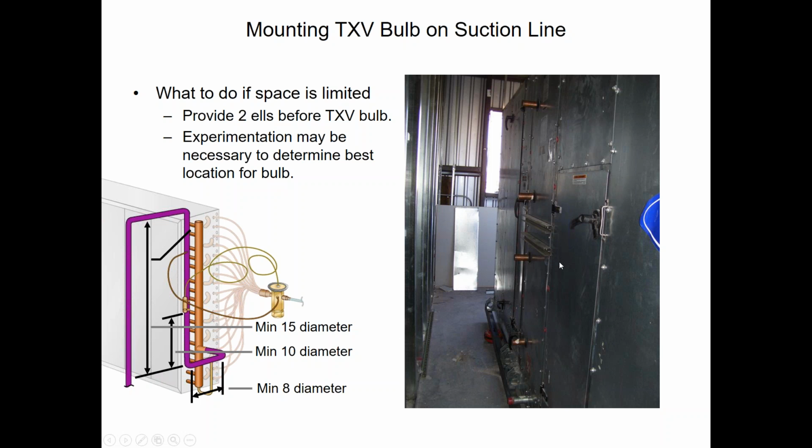Now, some of our larger air handlers, as you see the stub outs right here for the pipe, it's typically not how they come. They will come with just a blank door on the air handler. So you have to make the penetration through the door for your liquid and suction stub outs. Okay. So just a point there in the slide.